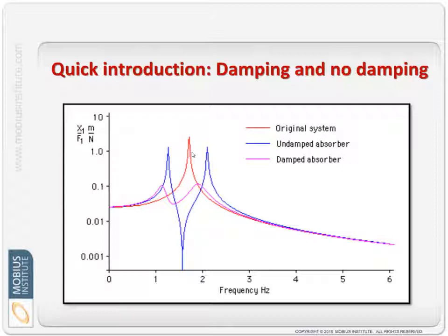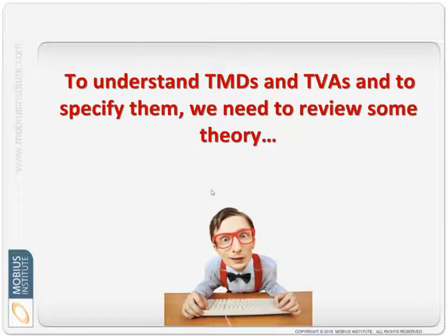So if, for example, the machine running speed coincided with this value, so the vibration was being amplified, and we used this solution, it would be a great solution. But with any variation in speed, or if we operate around this frequency, we've got a natural frequency. Whereas if we use damping, we get a better solution.